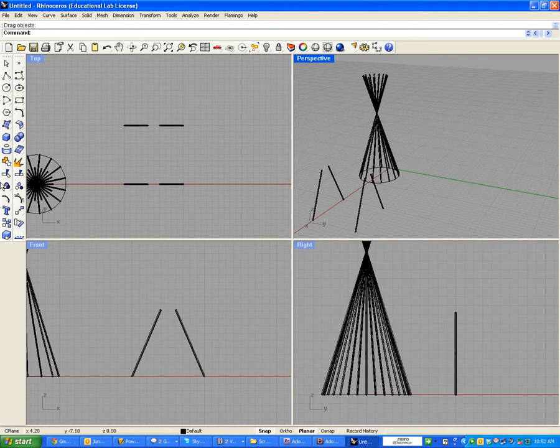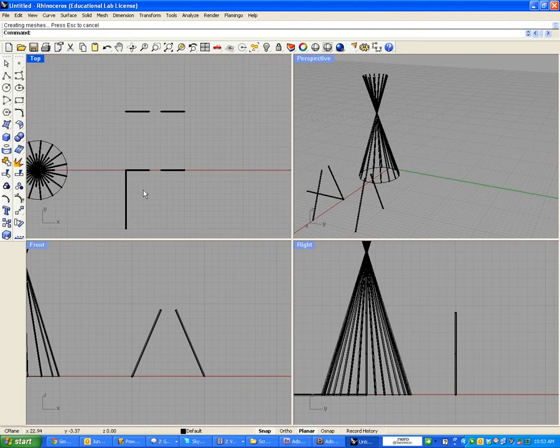Okay, now we're going to create another cylinder on the base of this triangle pyramid. So we're going to go to Cylinder, and we're going to create a cylinder on the front view. You want to locate yourself on X20, Y0. You're going to click there, and also 0.1 as a radius, and the length of the cylinder is also going to be 10. So in this case, we have our cylinder on this side, so we're just going to drag it and put it there.